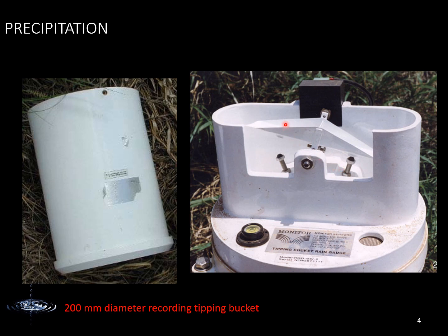And then because we know the volume of the bucket, we can calculate the rainfall amount. And we also will be able to see how frequently or how fast these buckets are being hit. And then from that, we can calculate the intensity of rainfall.